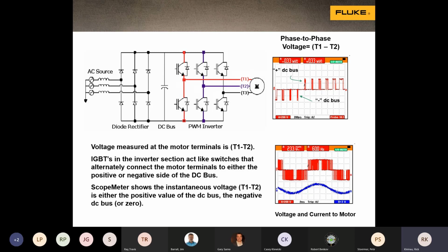But it's also just high frequency stuff going into a network that has a lot of capacitive and inductive components out there. You know, the motor is a big inductor. The cabling is capacitance. So I've got the carrier frequency, but also the switching speed of these transistors. These transistors are just switches. I don't have it written on the screen, but dV/dt, the change in voltage over time, is how fast the voltage goes.